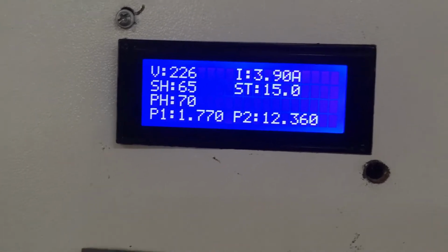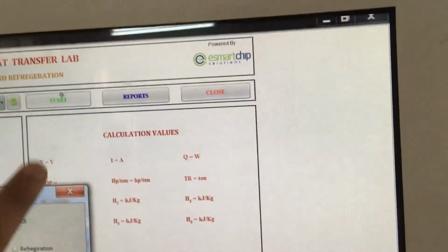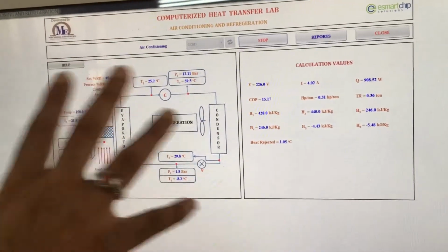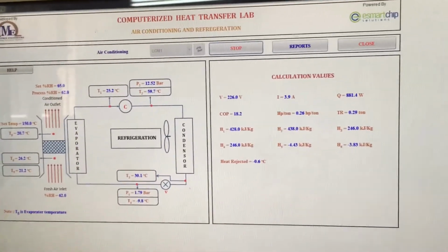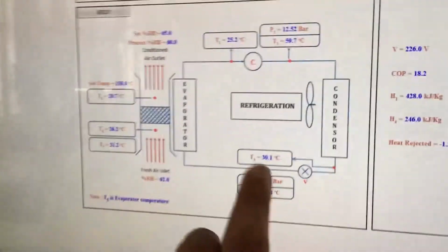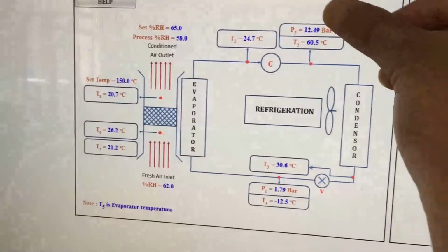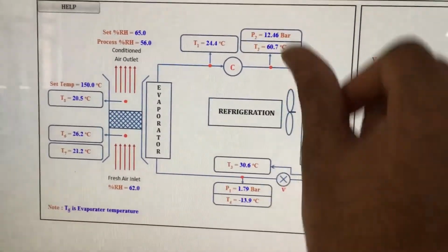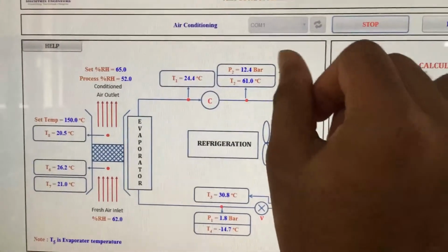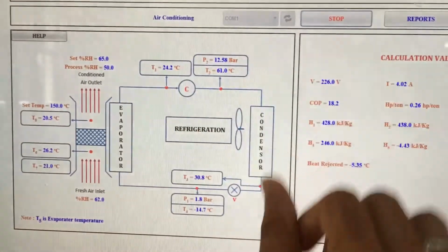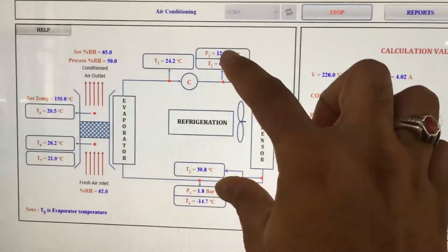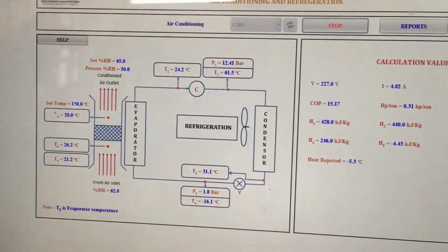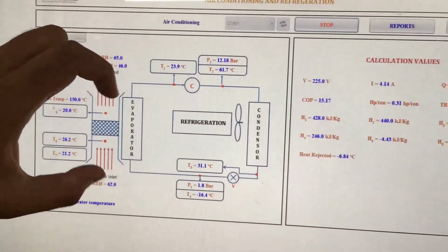These two pressures are at the two peak points, which can be looked at here, thereby setting up the air conditioning. The same temperature will be popped up down on the panels here. The pressure P2 is the pressure after the compressor, and P1 is the pressure after a throttle valve. You can see the comparison between these pressures. There is a huge difference between the pressure after the compressor and after the throttle valve. This difference in pressure results in a larger heat carrying capacity, that is the refrigerating effect, the heat which is absorbed here from the air.